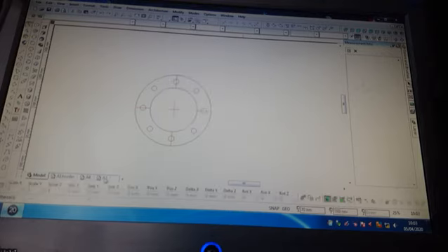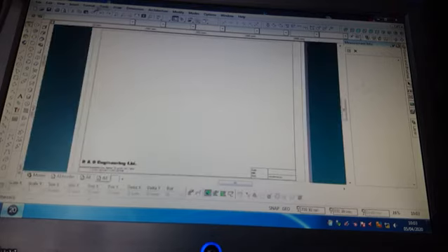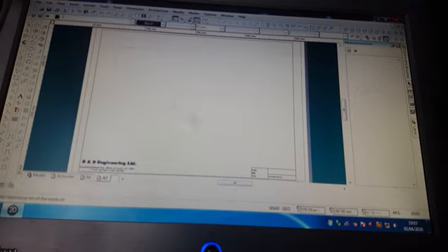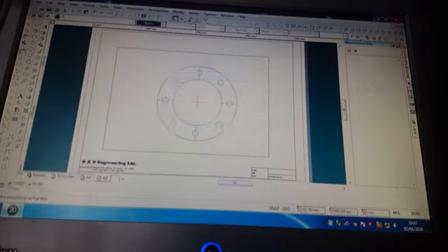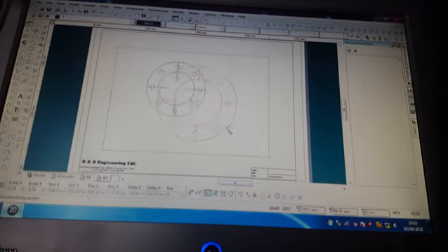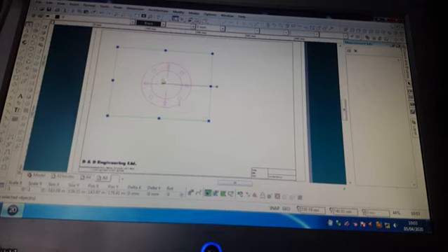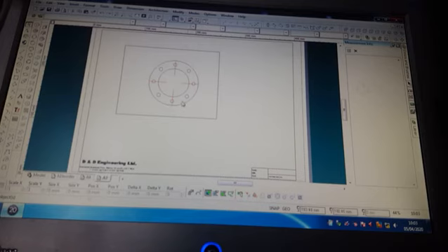And then we go to our paper space and we insert. No, I've got it on this little toolbar up here. Insert viewport, go to close. At the moment, space just to get the select tool. At the moment, the viewport can be expanded and contracted, moved around. But I want to do it at a specific scale.